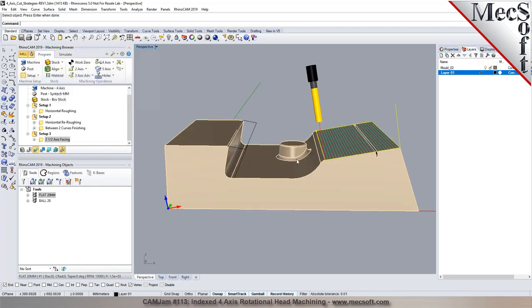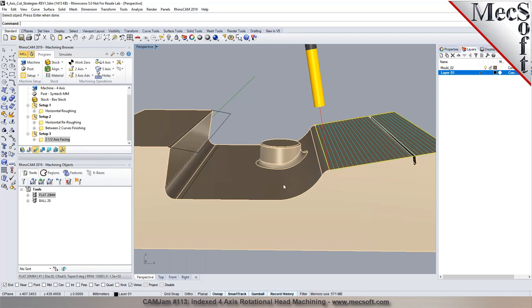And now we can apply a similar toolpath in here for finishing these sections as well, right? Yes, you want to flow along this. So I'd normally go over with the same cutter you've got there, the flat mill, and then go over it with the ball afterwards. I just leave a little bit extra on there, say 0.6.